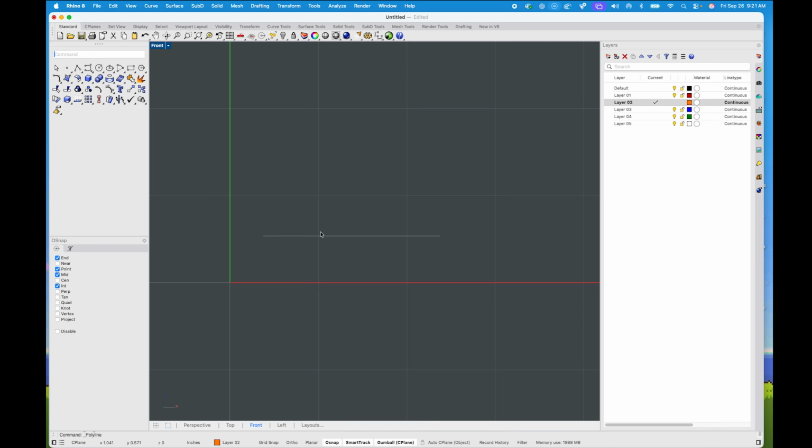So in our case, we've already used line. Let's use line again. Type in line. I'll click on this point and you'll notice that it kind of locked on to that point. It doesn't do this by default. In fact, let's go ahead and look at it. It's called O-snap, right? And if it's not turned on, you'll try to connect all day, but you'll just kind of sit there and be guessing, because it won't lock on to that point. As soon as you use O-snap, however, and type in line, it should snap to this point.